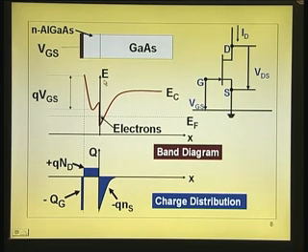Now, you can see this portion of the energy band diagram. Conduction band here dips down because of depletion, and also there are accumulation of electrons, that is the notch, and on this side you can see that there is a depletion layer. Just notice that the energy band diagram here dips down, means the field is in that direction. Okay.